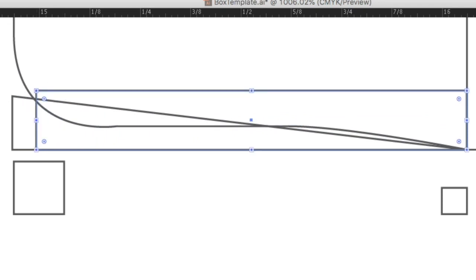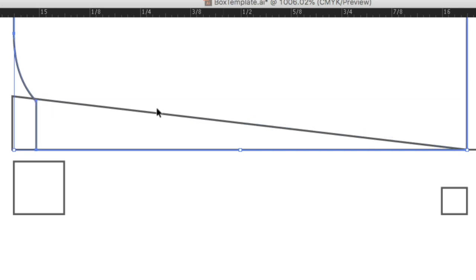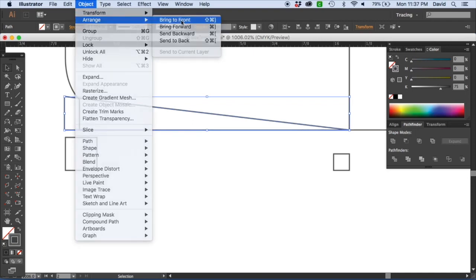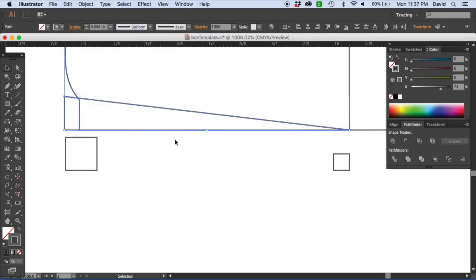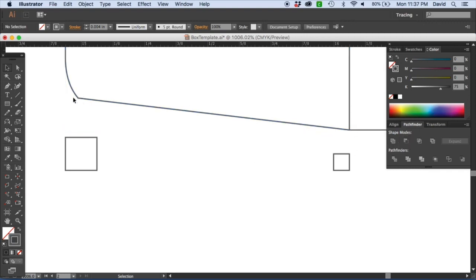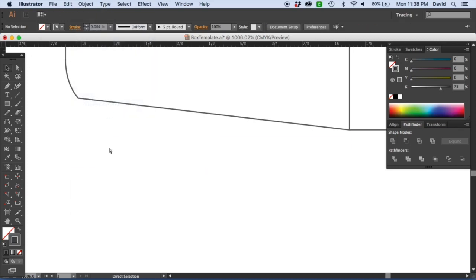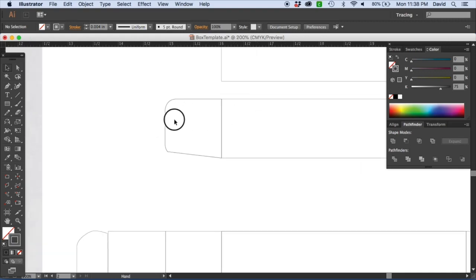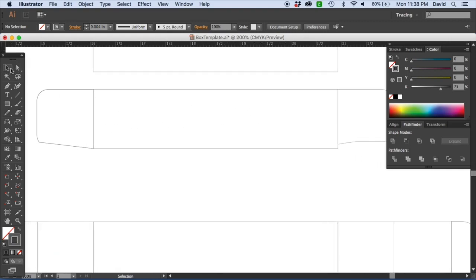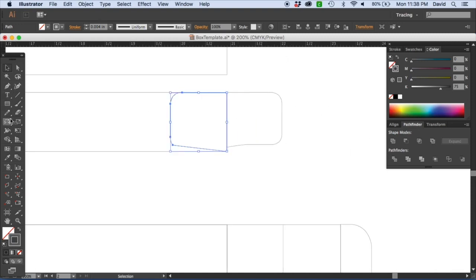All right, so I'm doing a little bit of a tricky thing here. I'm taking the tab and I'm actually adding some more shape to it. So now when I take out that shape, it's going to actually be a perfected edge like that. So that is now a clean edge from going from 1/8 of an inch to a 1/16. And now I can remove that guide, and now the edge is pretty clean. It looks really nice. I think it's going to work out great. So now I can go ahead and apply this to the other side. So if you need some more explanation on that, feel free to let me know in the comment section.